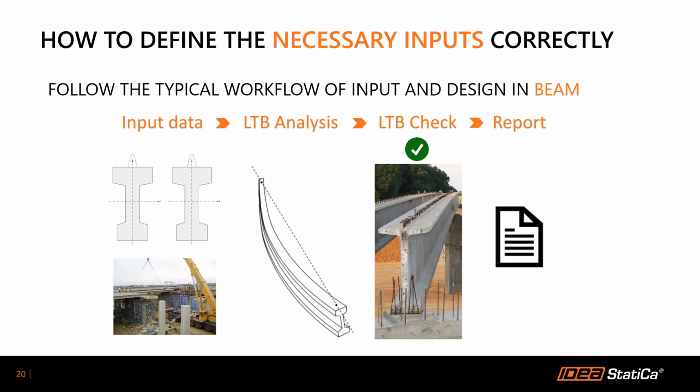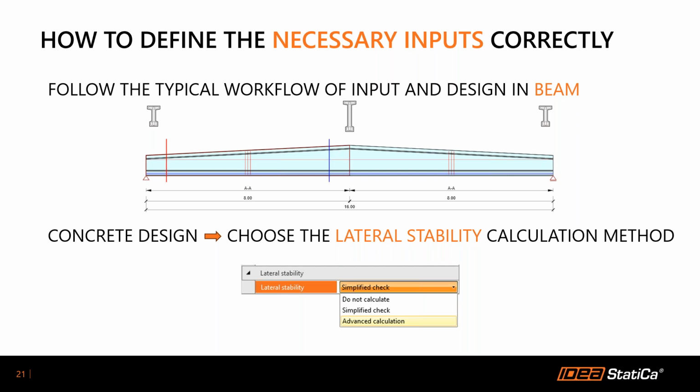So moving on to the more practical part of the webinar, I will show you how to define the necessary inputs correctly so you can easily use this design tool that was made for engineers to be used in their everyday work. So you would follow a typical workflow of input and design in the application Beam, as I will show you in a minute. So input of geometry, cross-section, supports, loading, prestressing tendons, combinations. Definition is the same as it used to be always. All the construction stages can be defined as usual.